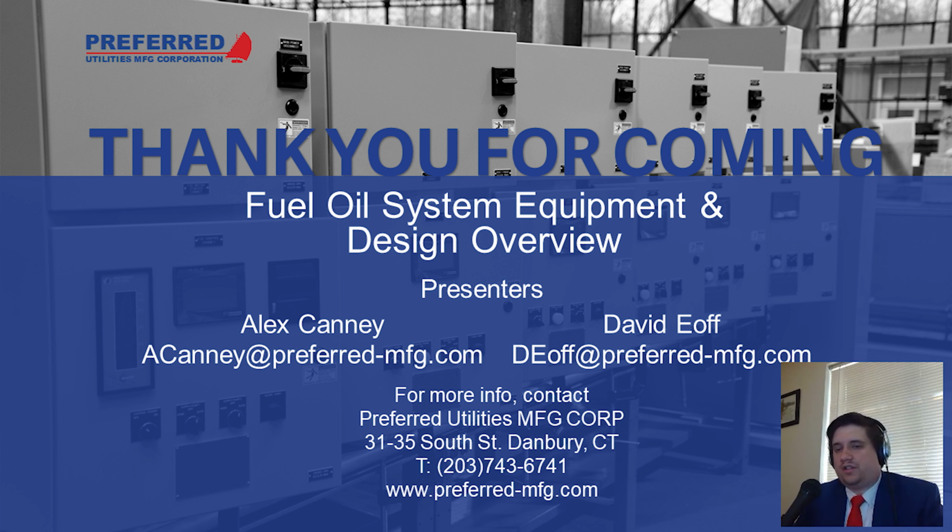Mark Charlin has a question on the chat channel as well. Is suction typically smaller than the discharge? And I think he's referring to pipe sizing. What I'll say is, in my experience, a lot of times they're about the same size. And the reason for that is, even though the suction side is very critical as far as how much pressure we have to work with and preventing cavitation, the size of the pipe itself on the suction side sometimes is less relevant than the size of the valves that are in there.